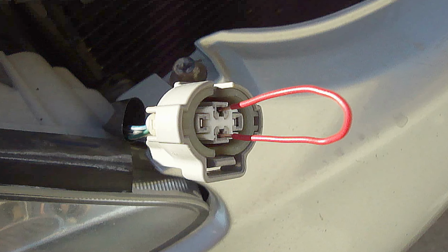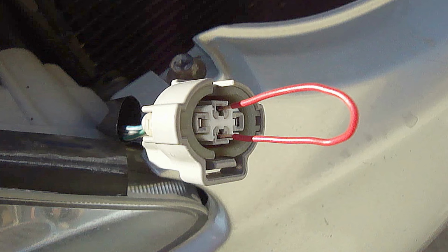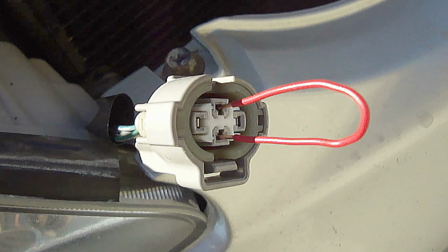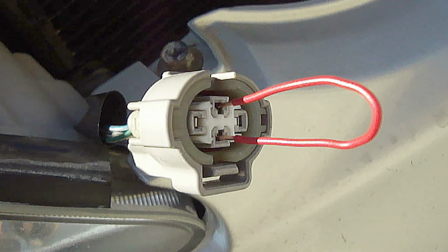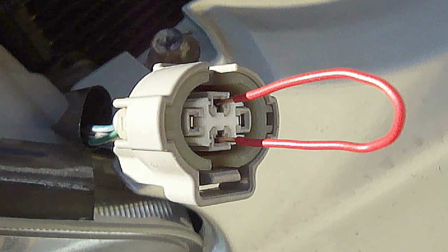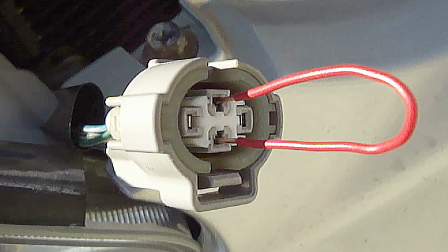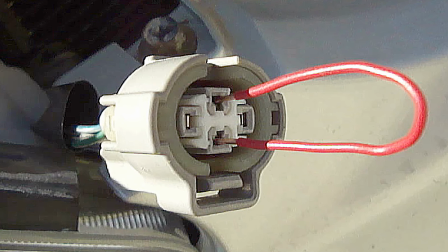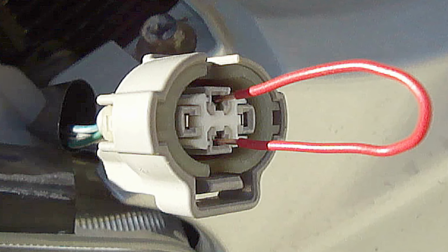Again, if the clutch will not turn, but starts turning when the pressure switch is bypassed, then you have a bad pressure switch which needs to be replaced. If the clutch does not turn after the pressure switch is bypassed, then the pressure switch is good and something else is causing the clutch not to turn.